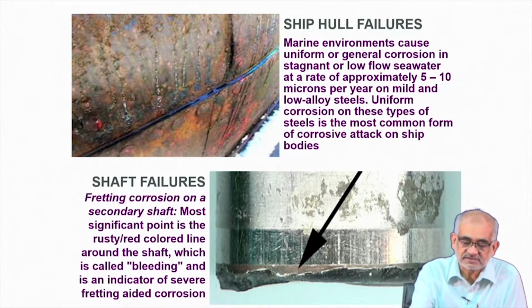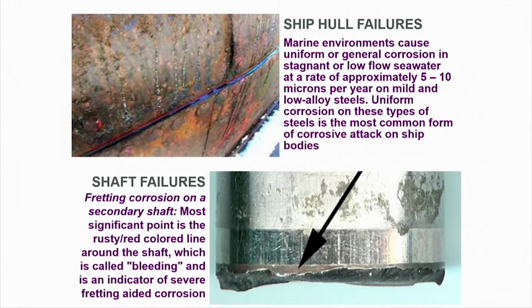So this is what we were discussing, that in the ship hull, this is the joint essentially. These are basically plates which are riveted, which are joined mechanically. So we certainly expect that corrosion can occur around these rivets, which may be compositionally different. And there's no necessity all the time that we have pure copper and iron. We may have copper based or iron based alloys which, in the electrochemical series, may form a galvanic couple by being one electropositive, the other electronegative, or cathodic and anodic.